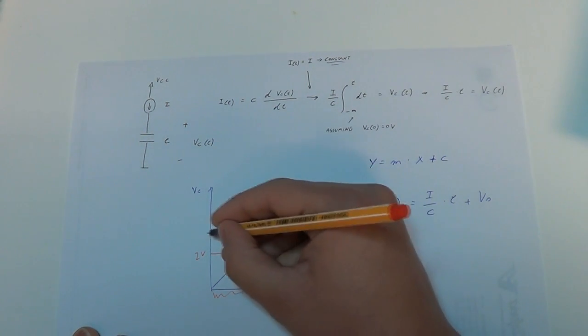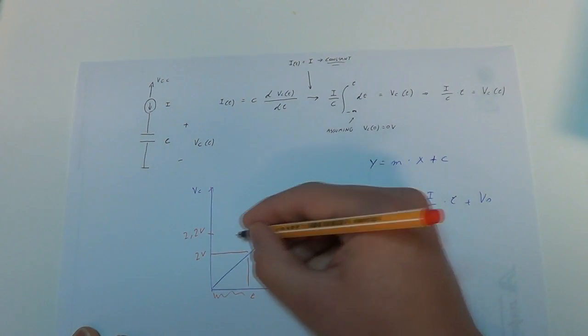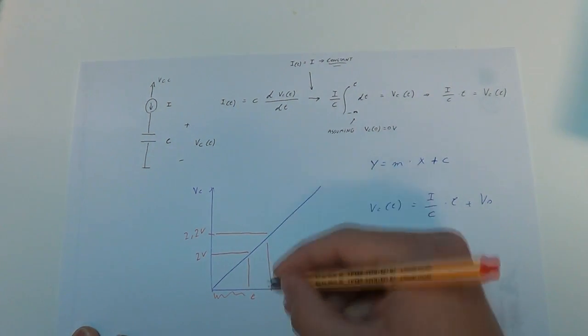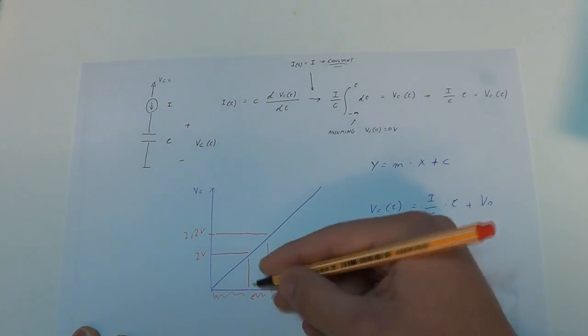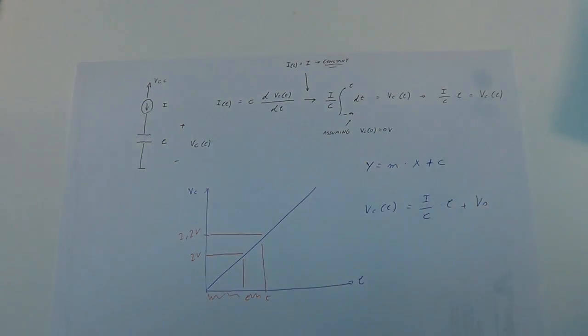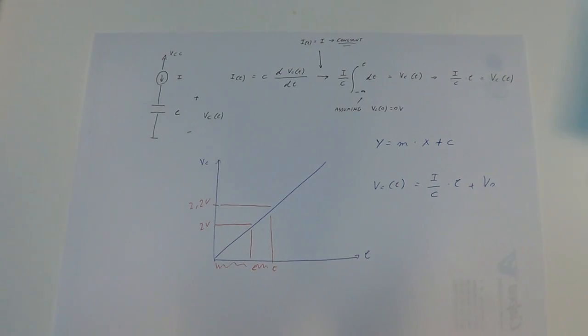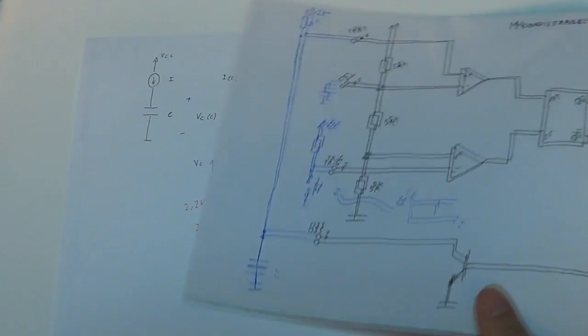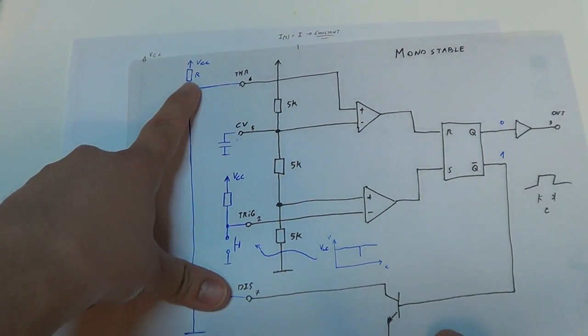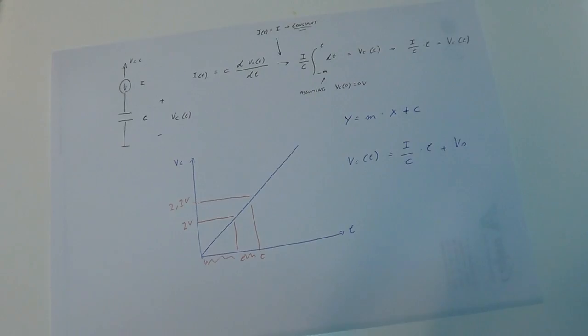And if you are giving it 2.2 volts it will have this amount, and as you can see it is linear over the entire range, and you won't have any problem with that. And as you can see, that is why my circuit is linear. It is because I replaced this resistor with a current source, and that is how I accomplish my voltage controlled pulse width modulation with very good linearity.